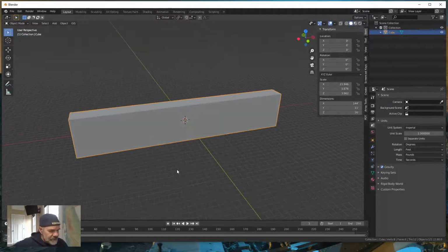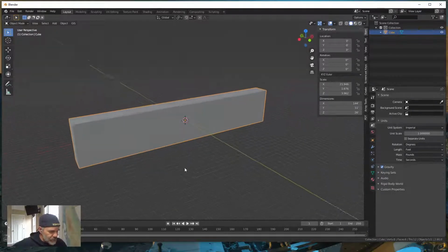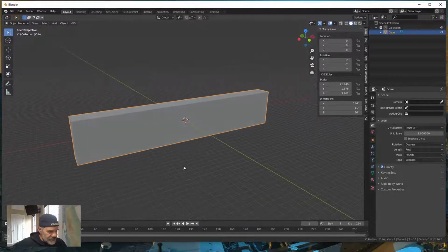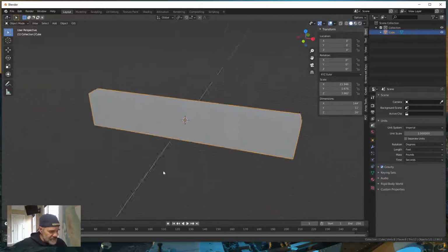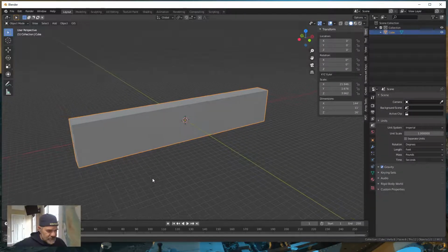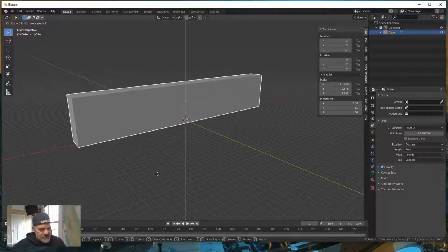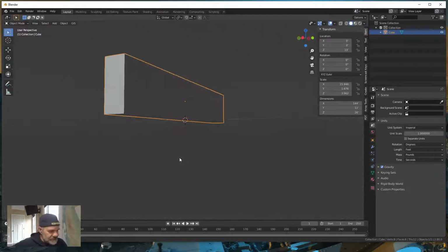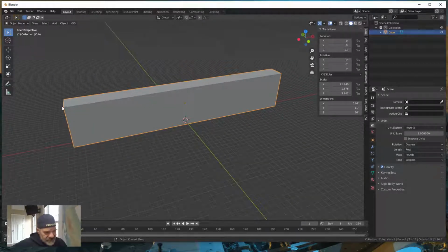Now in Blender, the origins are in the middle of the mass of that box, or that cube, or whatever it is now, it's no longer a cube, but a bar. So my building is 13 feet into the ground, since the height is 26, so I need to move that up. I'm going to hit G Z to move it up, and type in 13 to bring that up to ground level, just like that. Okay, so it's 26 feet on this end of the building.